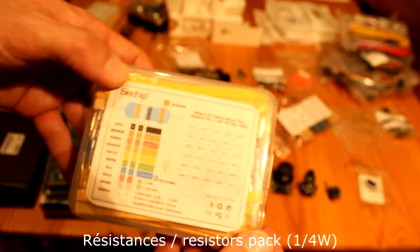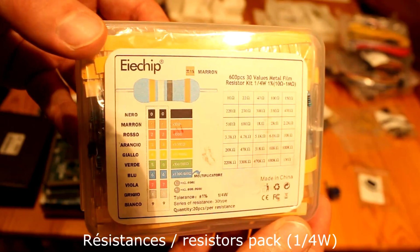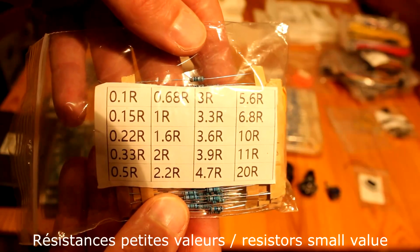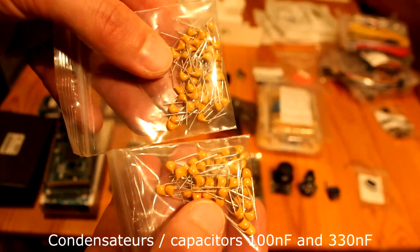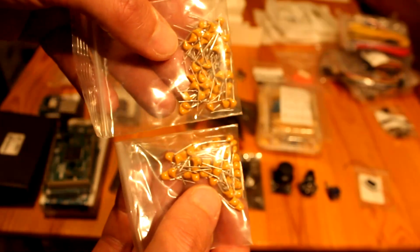This is a pack of resistors that I already had. We need several resistors that you can find on the wiring diagram, and at the end of this part I've put a table with the references. This is a small value resistors pack because we need a 6.8 ohm resistor, which is difficult to find. Then we have capacitors. We need 2 types of capacitors, 100 and 330 nanofarads.